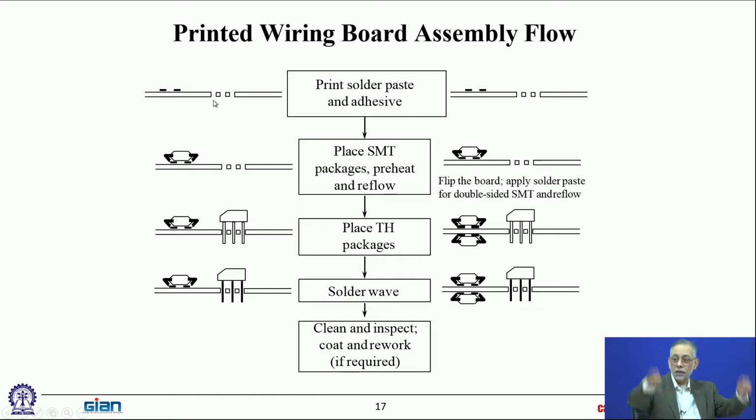And then you would lift the stencil off, and you'll be left behind with the solder sitting on the pads. Okay, so in this case, these are actually through hole, but here are openings for solder pads. Okay, so you would need stencils that had those openings, so you could put those solder pads down.